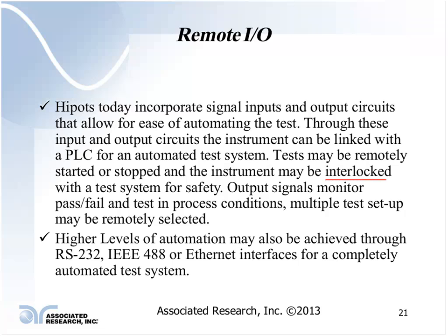Today, if you have an OSHA inspection and you have exposed energized circuits, and the operator can get shocked as a result of coming in contact with that exposed energized circuit, you can be held liable. You must provide personal protection equipment to protect the operator. So either you guard the product being tested, or you provide them personal protective equipment.